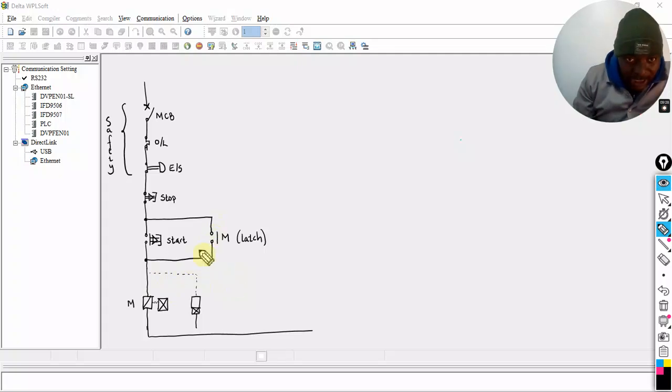So this is basically us starting, energizing the main contactor, and then the main contactor is energized with the timer. The main contactor is the one that carries the timer. Either it will be wired together with the electronic timer, or it will be a pneumatic timer embedded, sitting on that contactor. So I put them both, it's either that or that, not both.